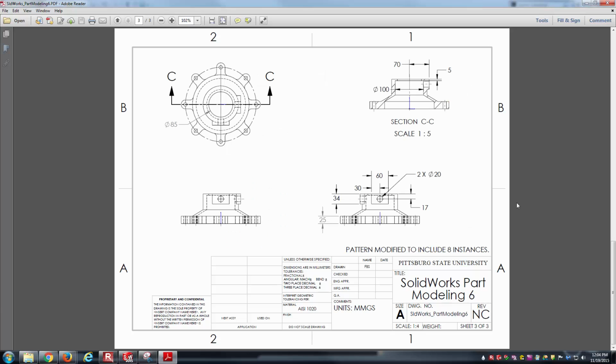And then after we get that modeled, we'll want to make the finalized part, which is config A here. And so here we've made a few changes. You can see the interior cut, the snap rings are gone, and also it's not just a simple cut. Now we've got something where it goes down with one diameter, then transitions to a larger diameter there. Also very noticeably, the tabs around the circumference of the part, or that base perimeter if you will, have moved from 4 instances to 8 instances.